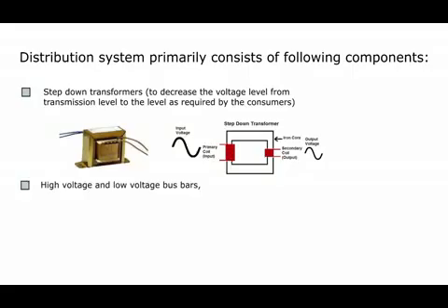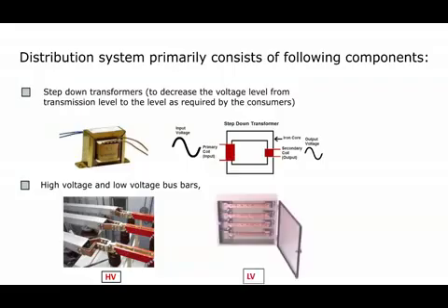High voltage and low voltage bus bars. These are metallic strips or bars typically housed inside switchgear, panel boards and busway enclosures for local high current power distribution. They are also used to connect high voltage equipment at electrical switchyards and low voltage equipment in battery banks. They are generally uninsulated and have sufficient stiffness to be supported in air by insulated pillars.